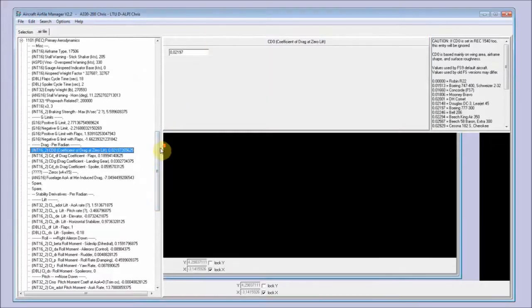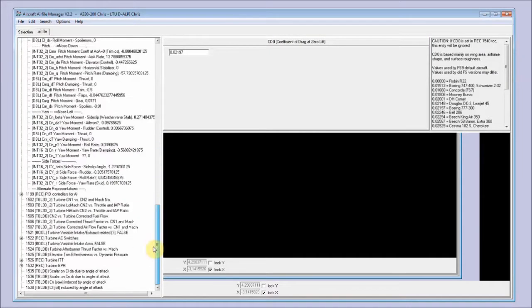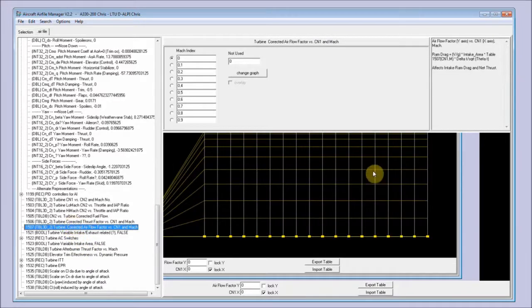So thereafter I had to adjust the ram drag, which is the ingoing impulse to the engine, and you can set up this value over here. The nice thing about this value is that it is independent of the engine parameters, just of the dynamic pressure, speed, and things like that.